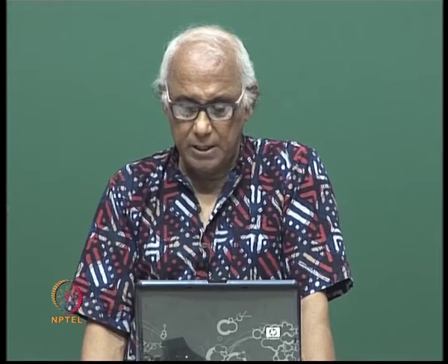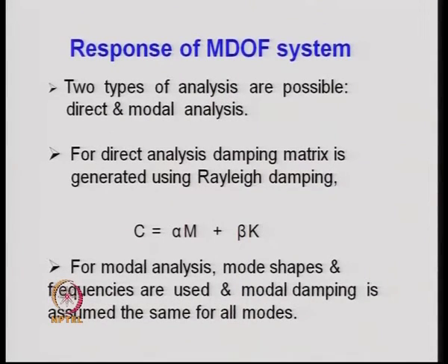In the single point excitation, we have the I influence vector or I influence matrix that generally consists of 1 0 1 0 etc. For multi support excitation, the I is replaced by R. R is a matrix that is called the influence coefficient matrix, and that is generally obtained by performing a separate static analysis for the differential support movement at the base, and how we obtain the value of R, that you have explained with the help of a few examples also.